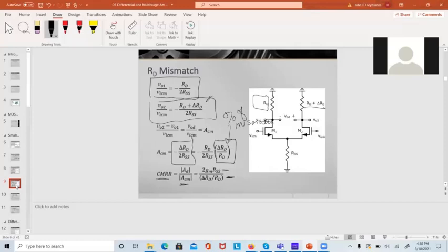That means your precision is probably good to about 1% of a nanometer or 10% of a nanometer. Then if I build a 100 nanometer transistor in that, my precision is still 1/10 of a nanometer. And so I can match things a little bit easier there.